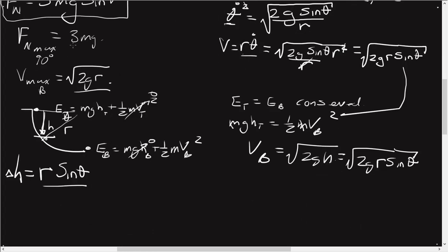And it's interesting that it's 3 times the weight. In fact, you could think of it as 2 parts. There's an mg, which would be your static, plus a 2mg, which is your dynamic, and that's due to the acceleration, the centripetal acceleration, and this is just your free body diagram at rest, normal force, holding it up.